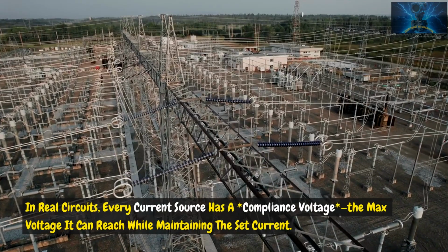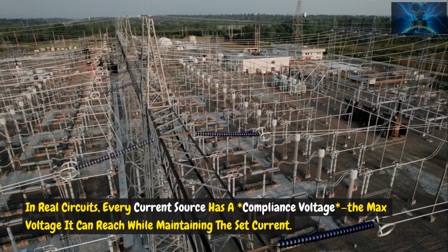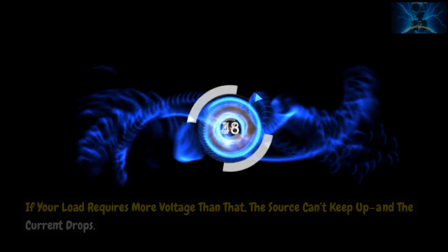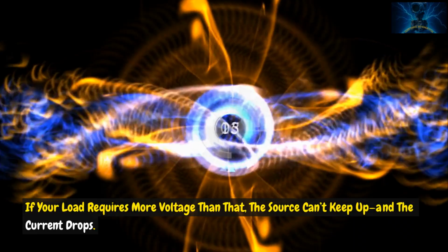Important: in a theoretical world, an ideal current source could provide infinite voltage. In real circuits, every current source has a compliance voltage, the max voltage it can reach while maintaining the set current. If your load requires more voltage than that, the source can't keep up, and the current drops.